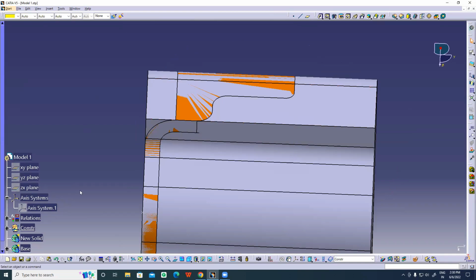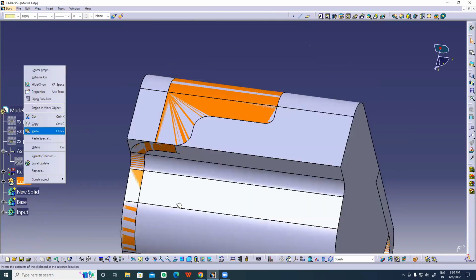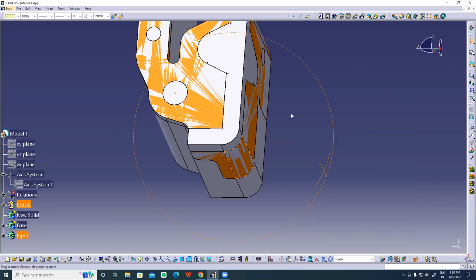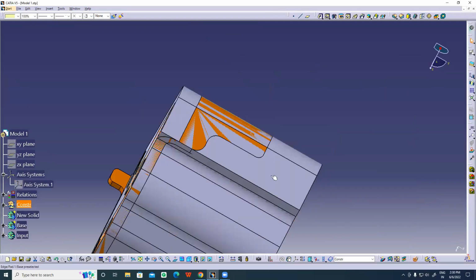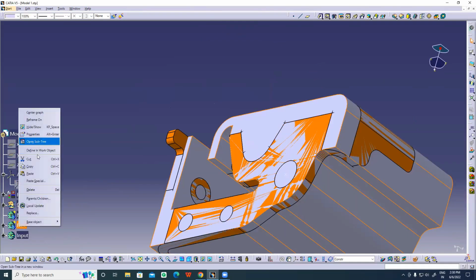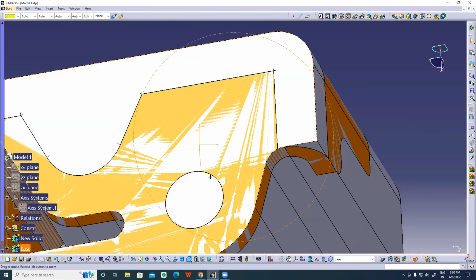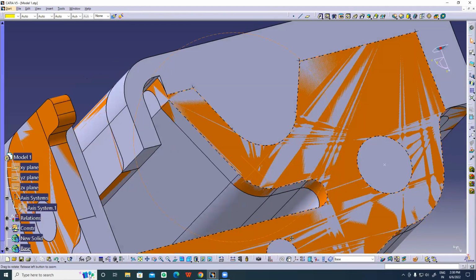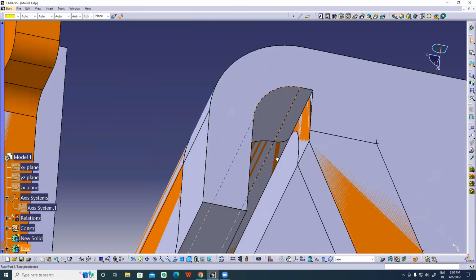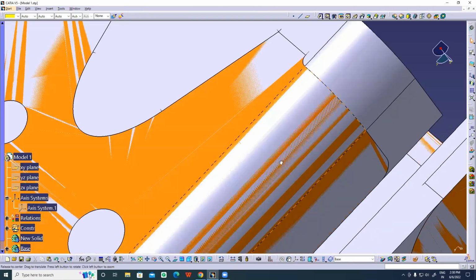Okay, fine. Now I'll be defining a construction, and I'm going to create this cutout first, the cutouts in the side part. Before that, if you are confused, if you wanted to apply a fillet also, you can fillet it. So let me define the base itself. Okay, and these are the fillets. It's a common fillet coming throughout these edges, but it's not coming throughout this edge. Actually, you can see I have to create a cutout in this portion. Only after the cutout can I apply a fillet. So I'm not applying a fillet as of now. I'll apply the fillet later.